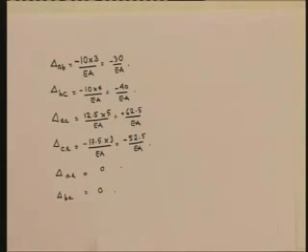Now let me ask you this question. This is something that we always tend to forget when we are doing structural analysis. Please note that you have to have dimensional consistency. Here I have said that all the EA values are the same, but I have not explicitly stated the EA value. What are the units of E?